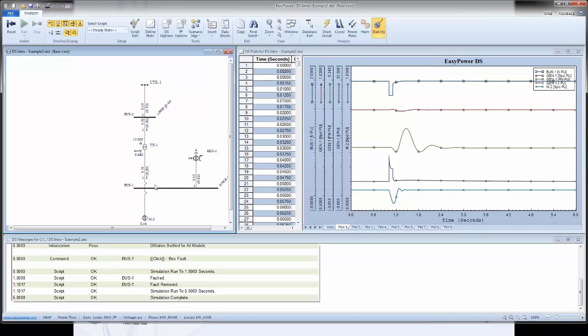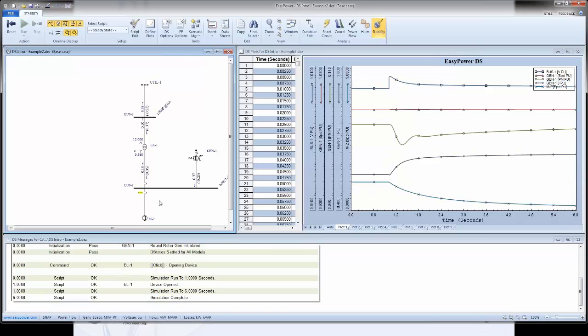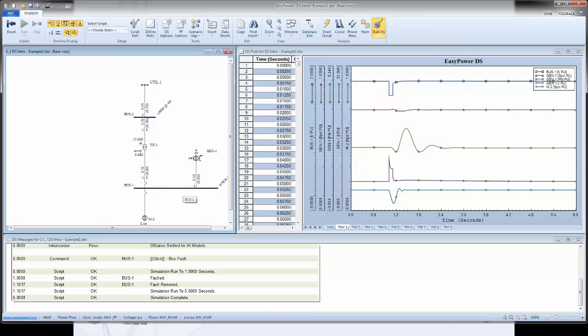If you want to make a difference, or if you want to open or close a breaker, you can simply do that and see the results, because this is another double click action. So okay, it has the power flow module in it. Short circuit, I can come here and create a short circuit. It not only gives me the short circuit results, but also gives me the waveforms, and it tells me what are the transient voltages, because the short circuit module is going to eventually give you the short circuit values, assuming that there is a short circuit current there, or there is a bolted fault current sitting there forever.